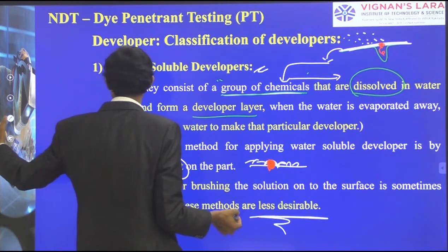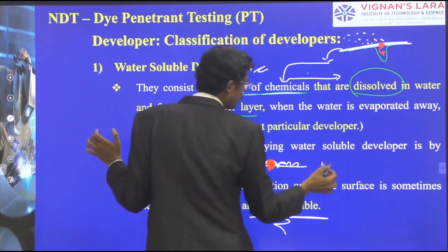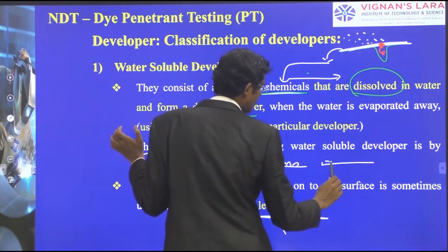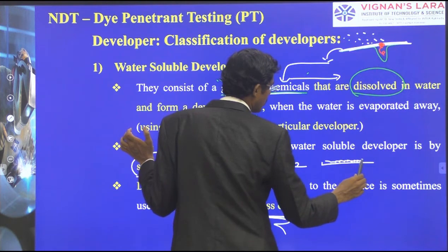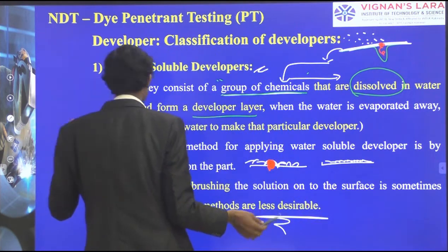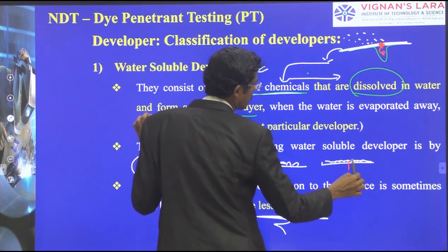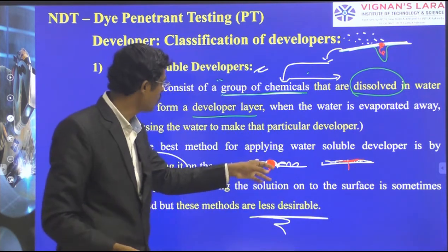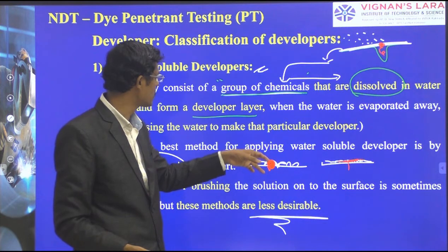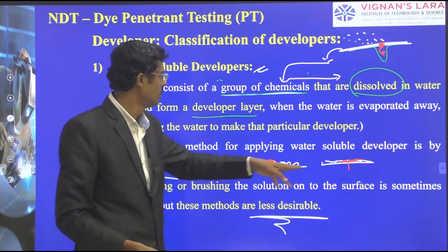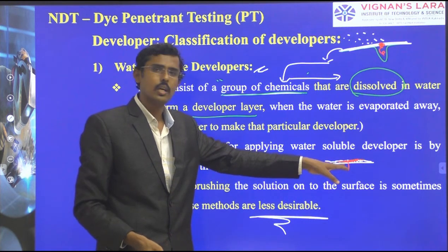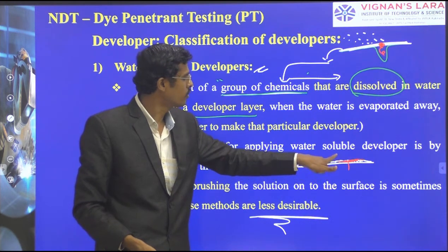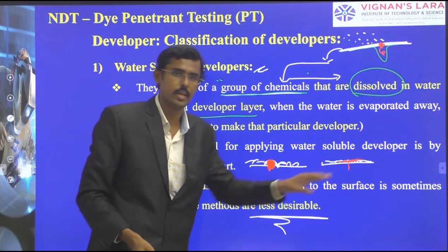But under the same condition, on the liquid, it is spread. Comparatively, dry powder has a denser penetrant at one cumulative point, but in the liquid water soluble condition, penetrant is spreading over and therefore density is spread.